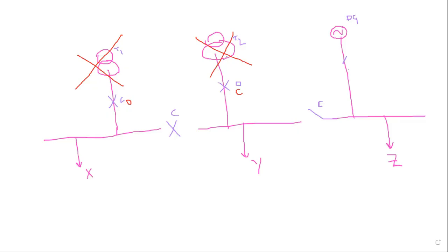Not only the transformer, suppose the breaker failed, or this feeder, the cable failed, whatever it may be, we don't know. Whatever it may be, the system has failed. So now this transformer is failed, and this transformer is failed. Now the DG set will come into the picture, and it will feed only my emergency loads. Emergency loads generally for the substation are some lights, illumination, and relays, all these things.